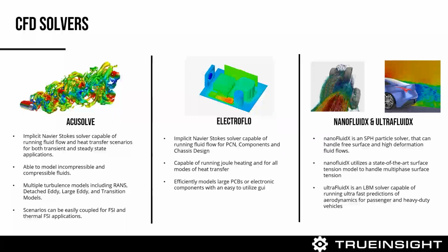Those of you who are existing Altair customers are probably aware of some of the tools you have, but you may not be aware that there are a number of CFD solvers within the Altair suite. The legacy solver that most of you are probably familiar with, if you know Altair's AccuSolve, is the default implicit Navier-Stokes solver. For typical fluid flow and heat transfer applications, it can run both transient and steady state applications, with the ability to model incompressible and compressible fluids.